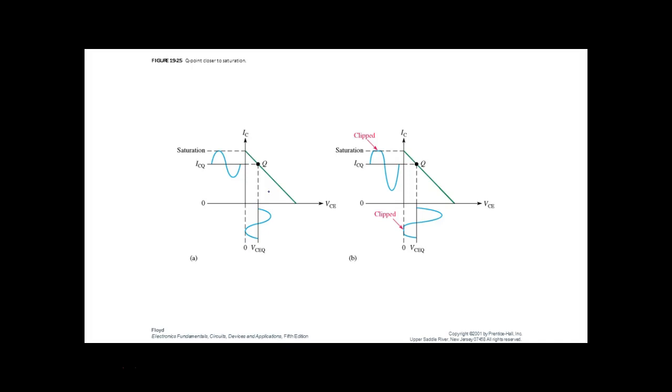So this is these really poorly designed transistor radios. People come here and crank them up, and it gets really distorted. Your sound gets really distorted because what are you doing? Well, you're either driving in saturation or cutoff. If it's biased in the center, you're still going to do that.